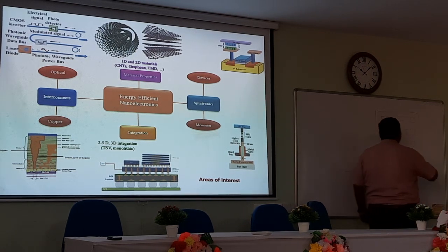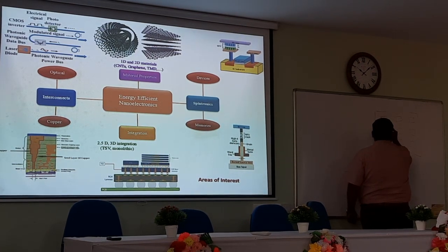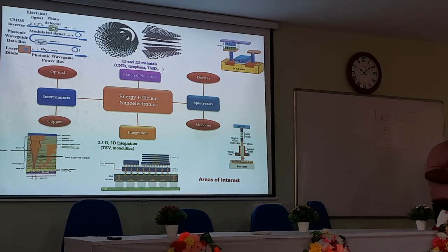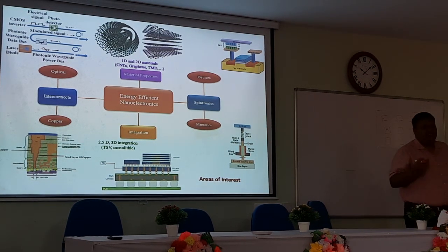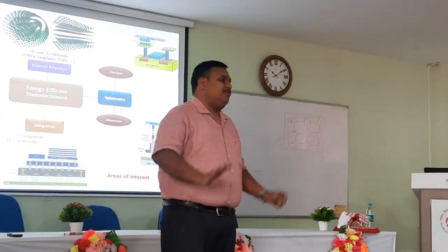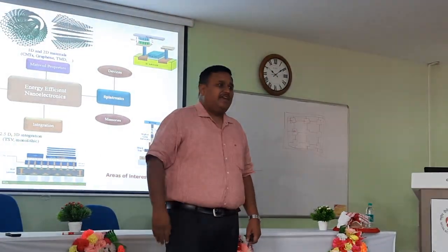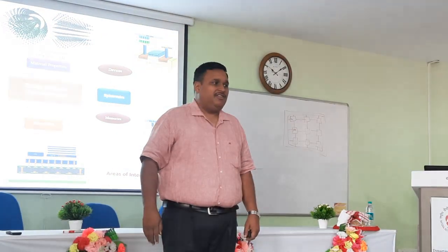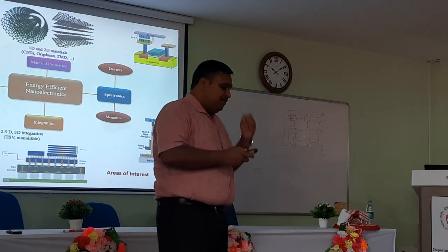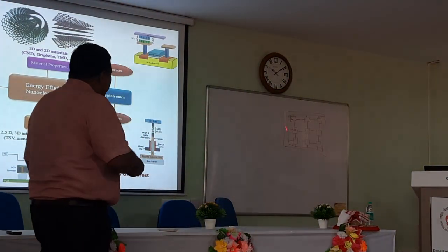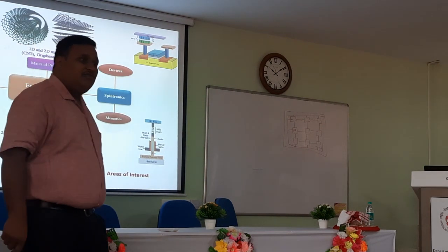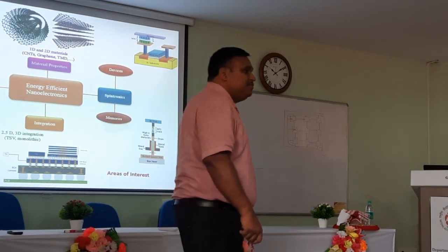Some might be memory, some might be ADC, some might be signal conditioning, analog circuits, digital circuits. There is a complete design team that looks only at the distribution of the clock. H tree, Y tree, this tree, that tree, every tree they do with the interconnects, right? So now these interconnects, once they have the resistive parasitics associated with them, what will happen?